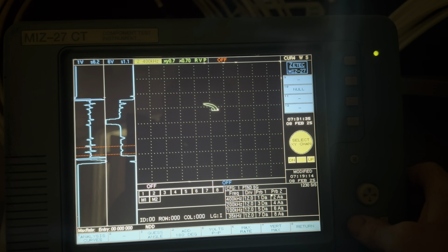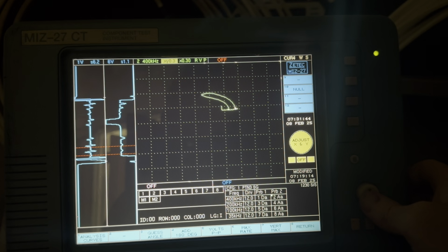Now we go to the absolute channels, 2, 4, and 6. So typically you would set these also to 40 degrees. But remember, this signal is a differential arrangement that's causing the signal, but the signal that we display here looks more like an absolute. But that's actually comparing a reference standard to your test coil and the actual tube that's being tested. So it's comparing the two, but it gives you an absolute type signal.